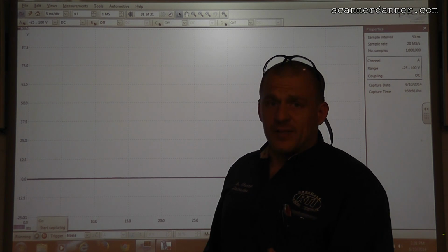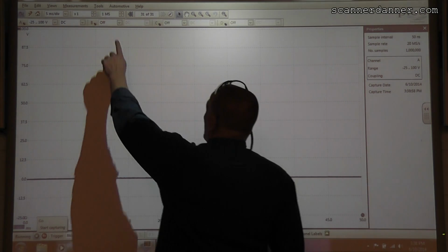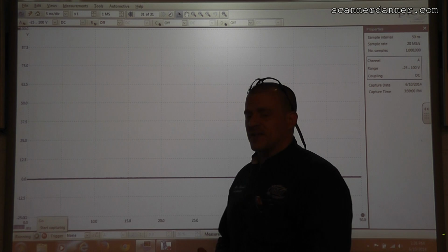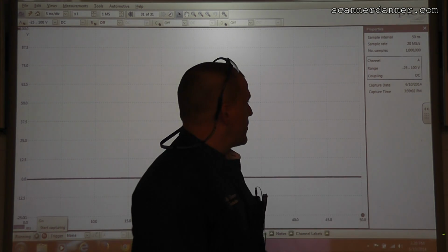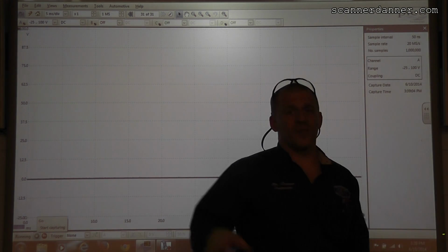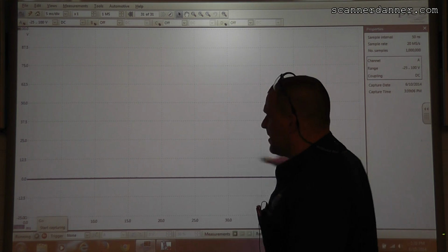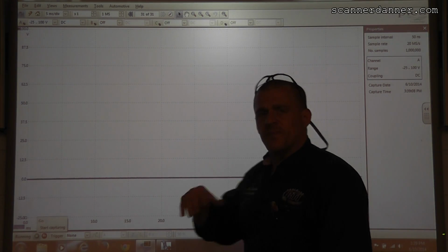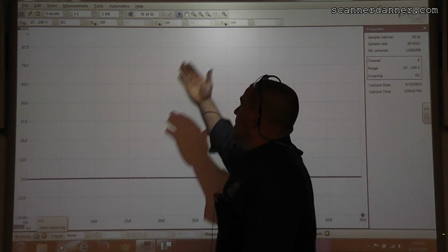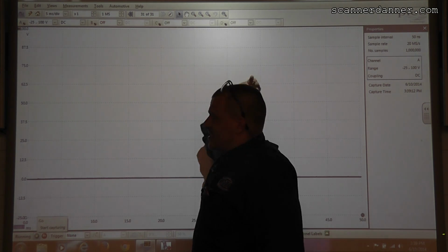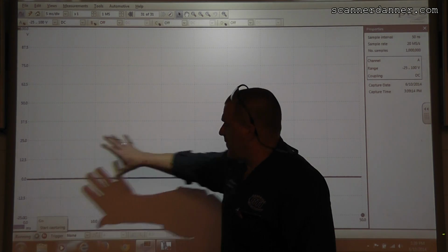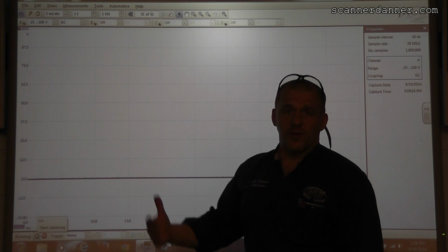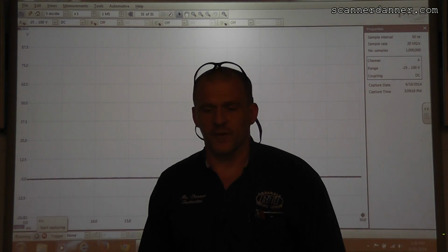That would be 32 million samples. It's 32 million samples because I'm set at a 1 mega sample setting. So 1 million samples on this particular screen. Each screen would be 1 million samples, 31 in memory, that's 31 million, and then the final one that we're looking at right here, there's our 32 million frames in our buffer.